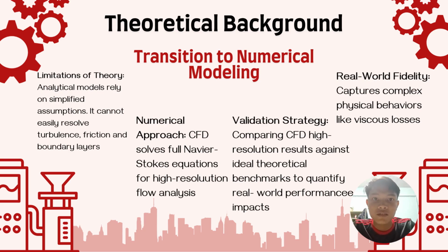However, these analytical models assume ideal conditions and cannot easily account for losses like turbulence, friction, or boundary layer development. To address this, we transition to numerical models using CFD tools like ANSYS Fluent. By solving the full Navier-Stokes equations, we simulate the actual physical behavior of the gas, providing a much higher resolution view of pressure and velocity distribution than hand calculations allow.